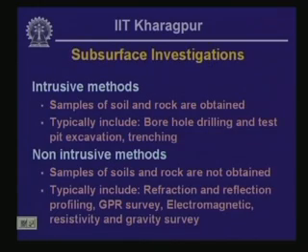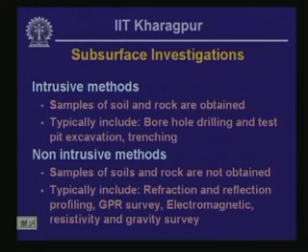Then we have to also carry out subsurface investigation to get more precise information about the elevation and the topography of the different stratigraphic units that are not visible at the ground surface. And also in this activity, samples of different types of geologic units are obtained for subsequent laboratory testing.